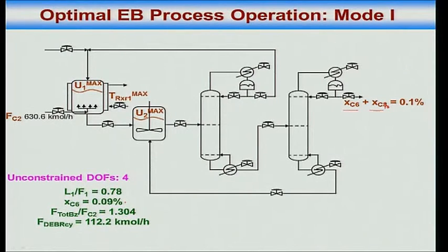Yeah? You see, I want the reactor temperature of reactor 1 to be max, because that gives me the highest possible temperature in reactor 2. Reactor 2 is adiabatic. Now, what is happening in reactor 2? Reactor 2 is basically transalkylation, the last reaction. So if the last reaction is fast, what that means is I will not be having that much DEB accumulating in the recycle loop. I don't need to accumulate it to that large an extent to balance the consumption.